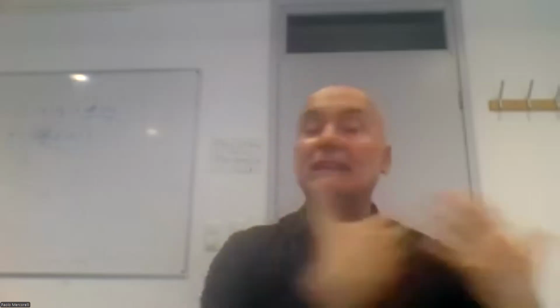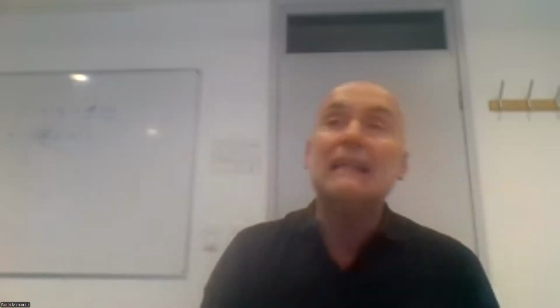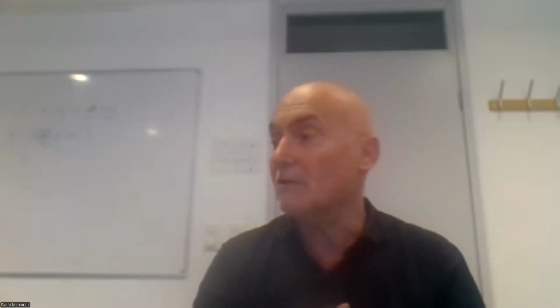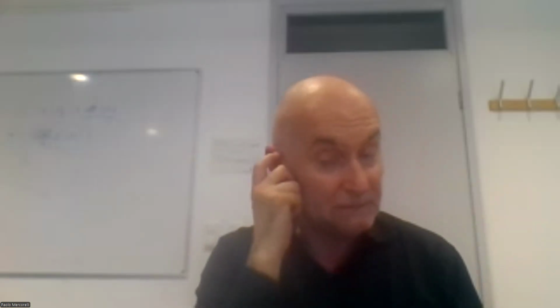But I would like to tell you a little bit, fleshing out what the idea is, because it's extremely important. Why is it important? Because we cannot know the system perfectly. We cannot know the parameters of the system perfectly, even though we can estimate and update. The Kalman filter is an alternative form that can also combine adaptively its behavior to estimate what we don't know, and to estimate the state.